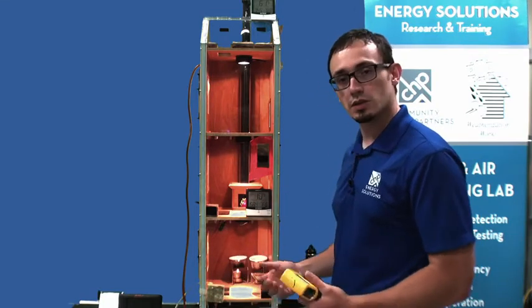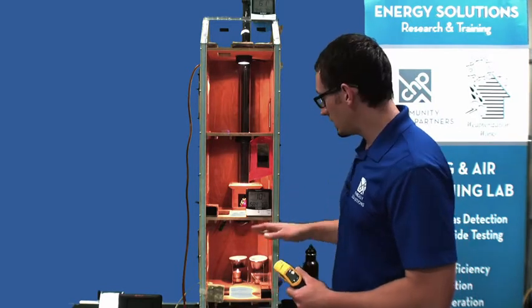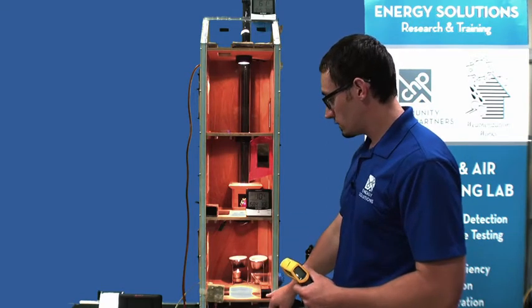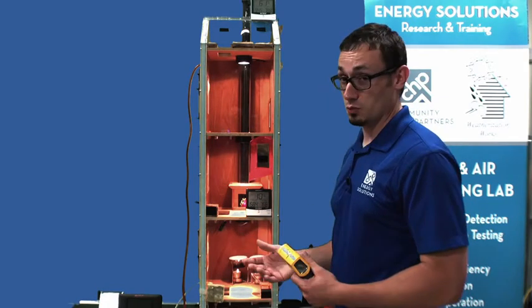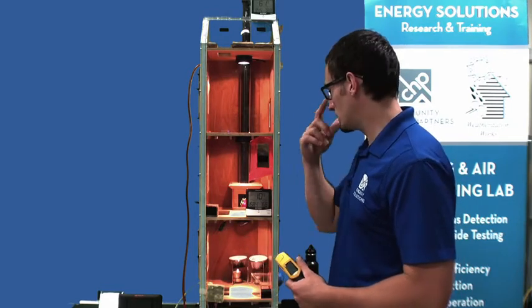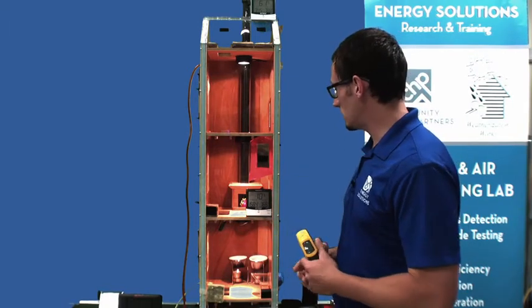I'm only at 10% relative humidity. It's really, really warm inside the house. I'm not there. So I have to get either this surface to drop in temperature, or I'm going to have to add humidity here. 10% is really dry. That's not something that you're typically going to see in a house. So what we're going to do is explore some other surface temperatures here and just see what's going on.